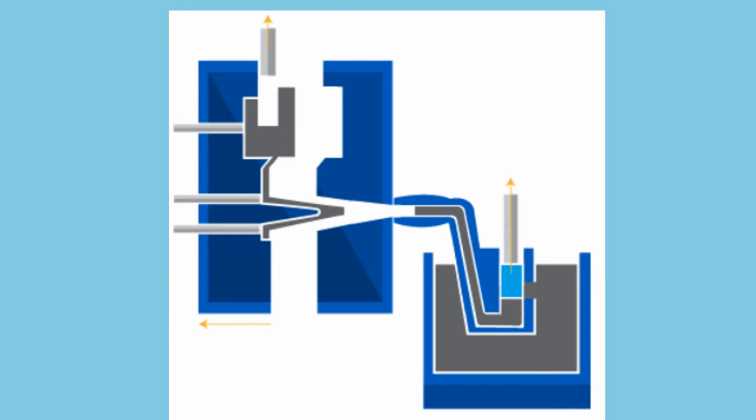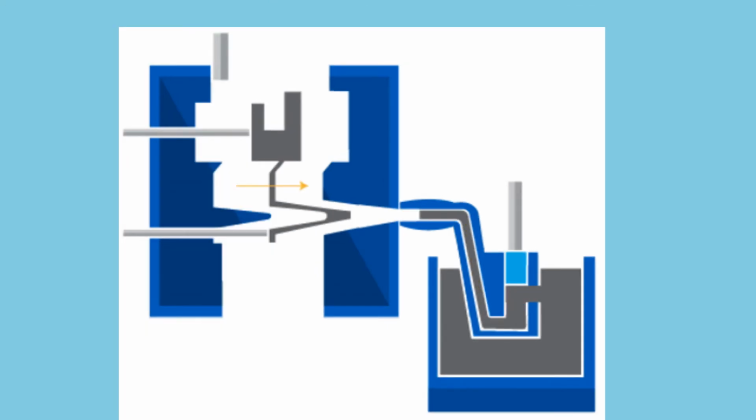So here is an example as to how the ejector die removes itself. And you can see that any leftover molten metal has stayed within the gooseneck and partly into the nozzle, and that the core has also been removed, which creates this void in the product. Now let's go back to these ejector pins, because what will happen is the ejector pins will then push the product out of the mold, which is why it must be well lubricated with some form of releasing agent.